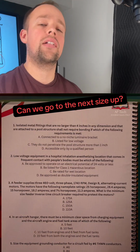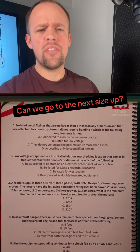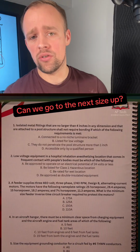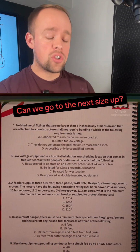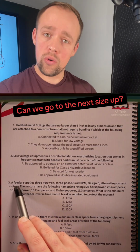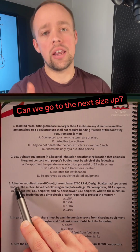If you are a journeyman electrician or a master, this is going to ring some bells. You're going to know, oh yeah, that's the next size up rule. We use that all the time. And this guy challenged me. He said, hey, you didn't round up, therefore your answer is wrong. Well, I am going to challenge that line of thinking and say, hold on, for certain cases you're correct. But remember, we are sizing the feeder overcurrent protective device, and that particular code article doesn't say that we can round up. So let's open up our code books and I'll show you where.